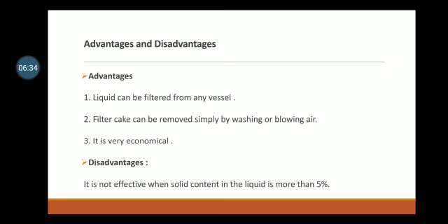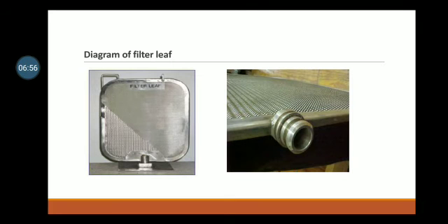Advantages and disadvantages. Firstly, advantages: the liquid can be filtered from any vessel. Filter cake can be removed simply by washing or blowing air. It is economical. Disadvantages: it is not effective when the solid content in the liquid is more than 5%. This is the diagram of the filter leaf.